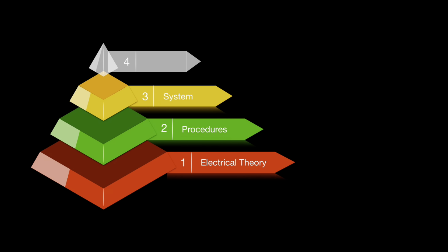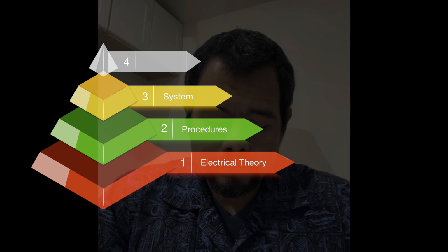Third, the third layer consists of knowing the system. What do I mean by that? Understanding what voltage systems are utilized by the control center. Understanding the layouts of the circuits and where they run, how they're interconnected, and how they affect one another. Understanding the load patterns within the control center environment. You may have different industrial load centers, you may have residential load centers, you may have commercial load centers, and how the load flow characteristics according to each area change according to times, seasons, weathers, and so on and so forth. Load related considerations and issues.